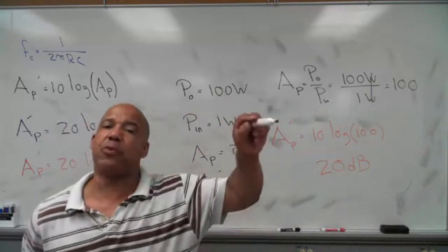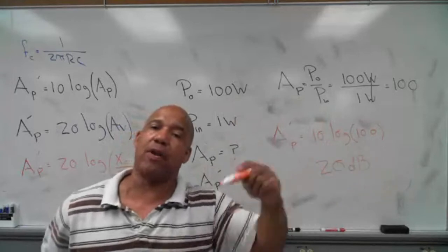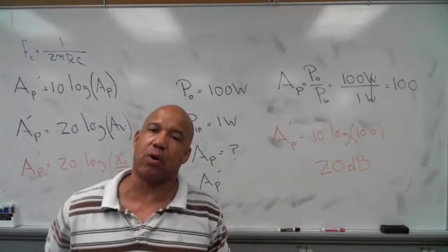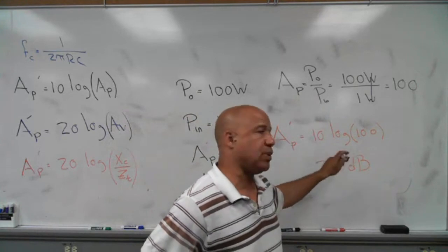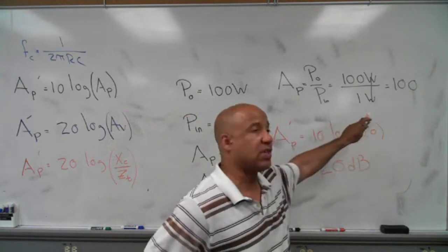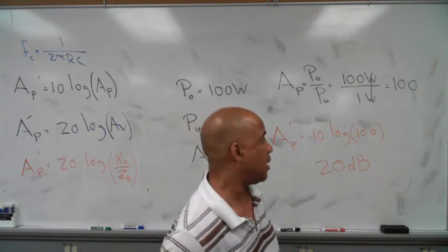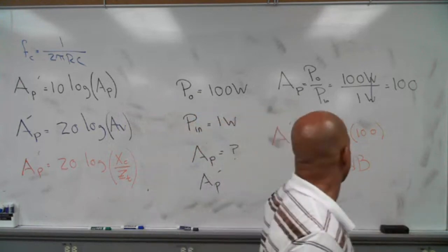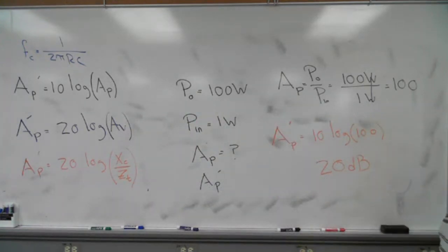Every time you go up 3 dB or down 3 dB, you either double the power or halve the power. So dBs are easy to work with. So if I go up, say 21, 22 to 23, whatever the power is, if it's 100, we'll go up to 200. There's a doubling for every 3 dB, or halving for every negative 3 dB. Does everybody see that? That's an easy problem to do. If I gave you that on the quiz, you can do that all night. Nothing hard about that one.